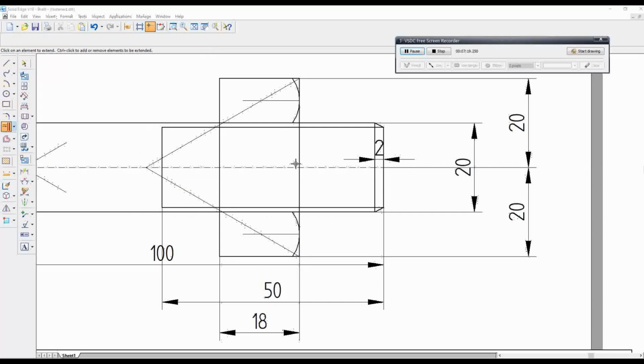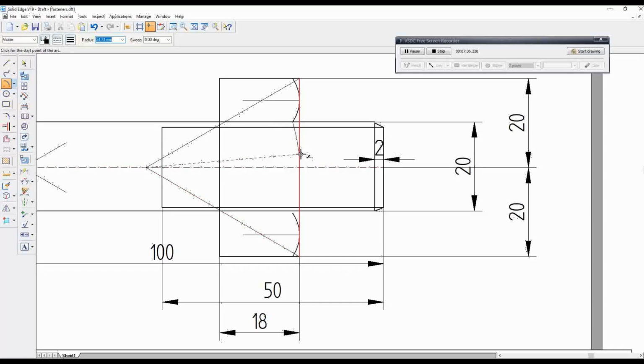And next step, we have to make chamfer for the center portion. So anyhow we have the intersection point from this 30-degree line. So go to arc. Exactly this is the radius, the center radius. So draw arc on either side. Yeah, connect. So now make these two lines as dark. Two arcs as dark. Now trim the extra portions, unwanted portion.